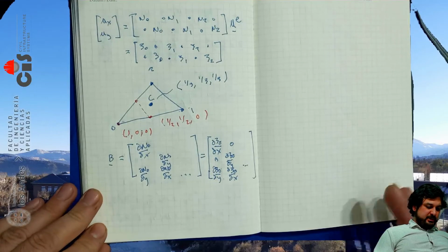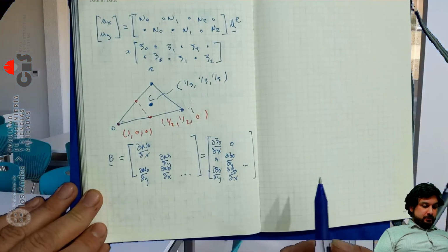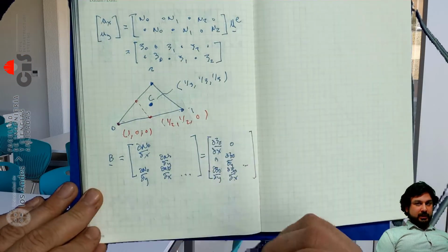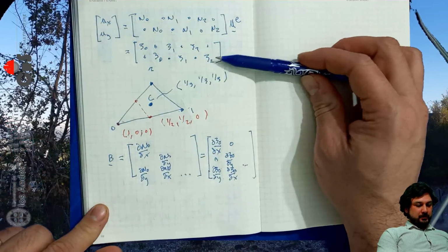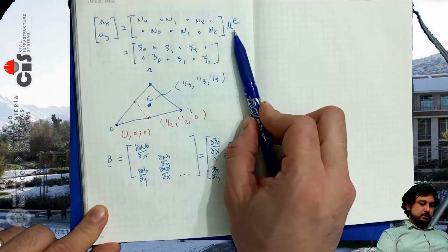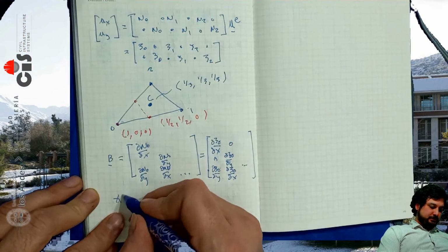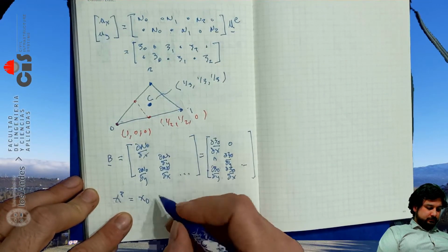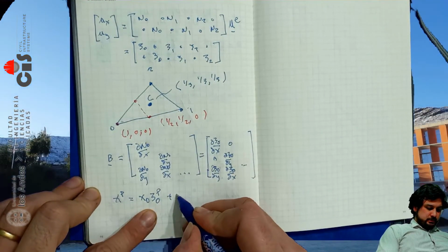So the way we get these derivatives is thinking about how you interpolate geometry. If I know the triangular coordinates of a given point, how do I get the global coordinates of that point? Well, the idea is similar to what we have here. I can just write x and y, and here I'm going to have the xy coordinates. So basically, the x coordinate of a point, whatever that point is, is going to be x0 multiplied by the triangular coordinate of that point, plus x1 and so on.